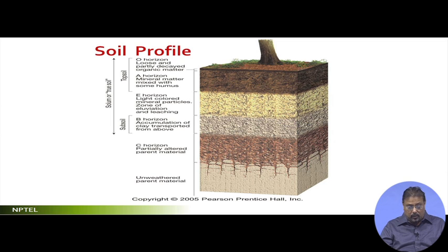soil stability, in such cases, for geotechnical investigation, what you do is you take the soil in the undisturbed situation. You break the soil and then you take it to the lab, and then you are trying to find out the stability of this. It is meaningless, because by breaking it you have already added air into it, and the particles' stability, structural bondage, you have broken. And once you have broken the structural bondage, you have no reason to study the structural strength of this or the structural bondage of this.